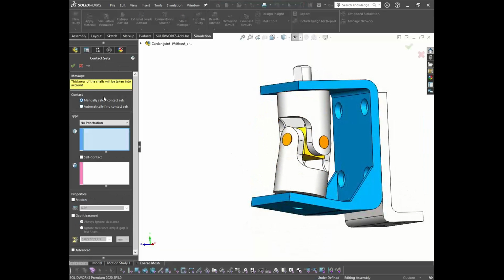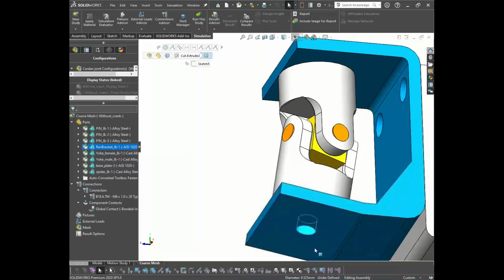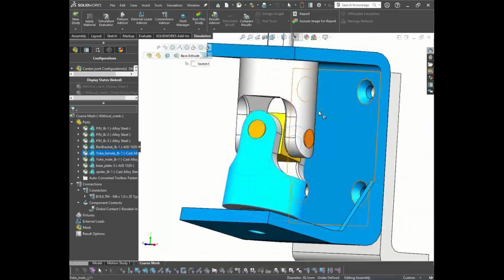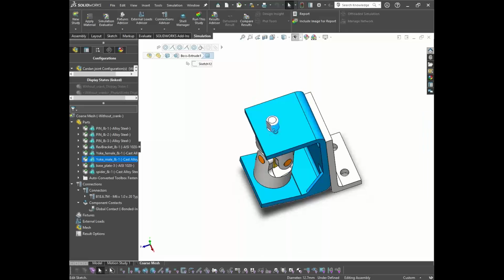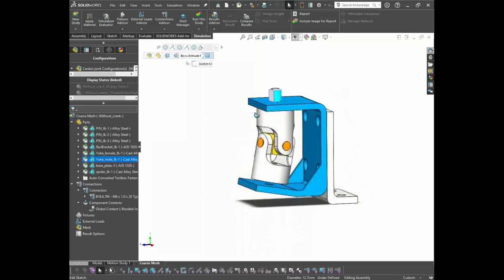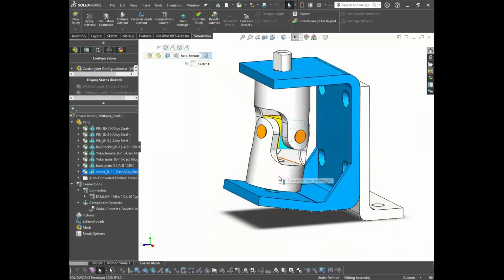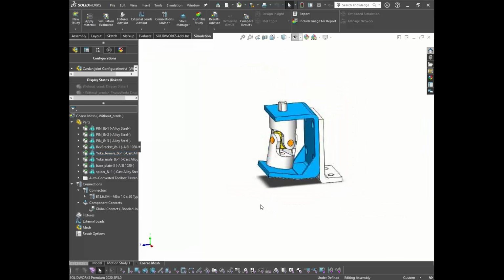And since there are a number of no penetration contacts, as you can see, this yoke will rotate with respect to this. This will be the pin point for this yoke. Again, when we are applying the load, this will try to rotate in the Y-Z plane, which will additionally rotate this yoke. Since it is connected with the pins and this spider, it will try to rotate this, and again this will incorporate the motion in the downward direction. So we need to consider all these motions.